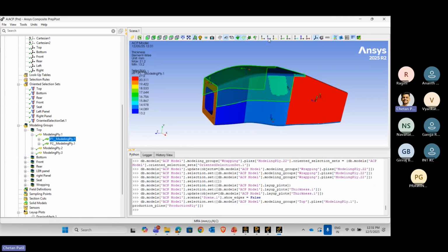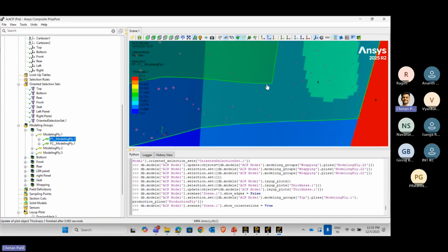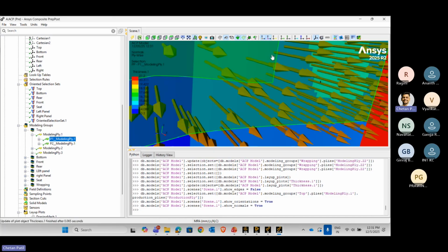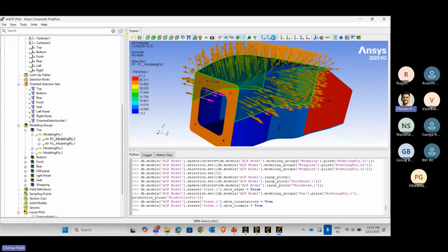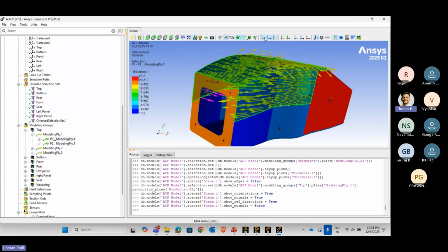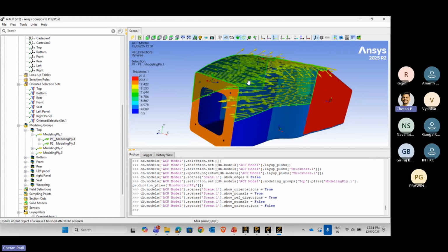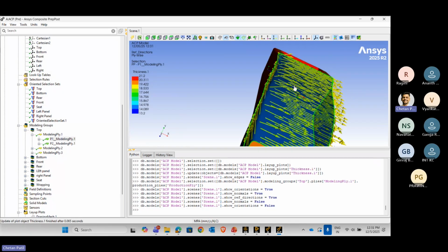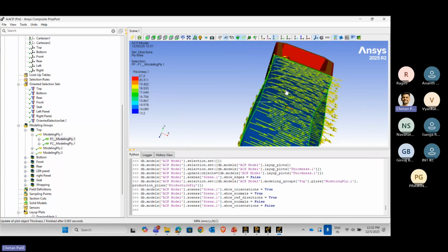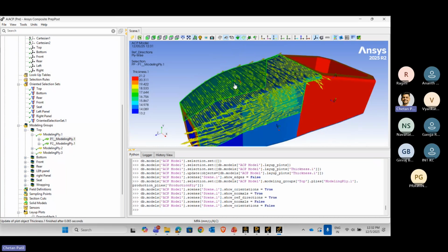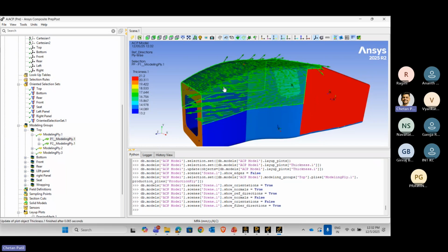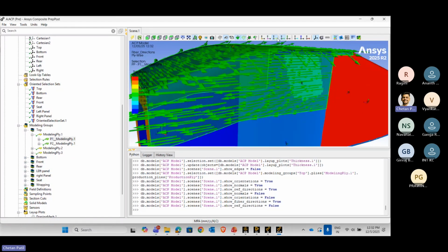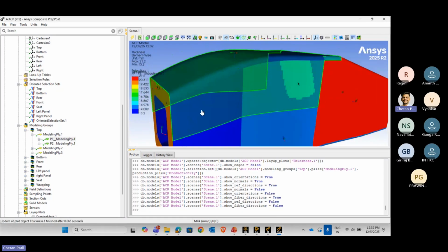You can even see the direction of the plies that you have created on the model. You can apply this to the regions where the ply will be oriented, and see the directions of your ply. Over here you can see, with respect to this region, in which direction the plies will be created. Due to the draping that we have applied on the model, the fiber orientation is not getting much changed. That's the advantage of using the draping condition.